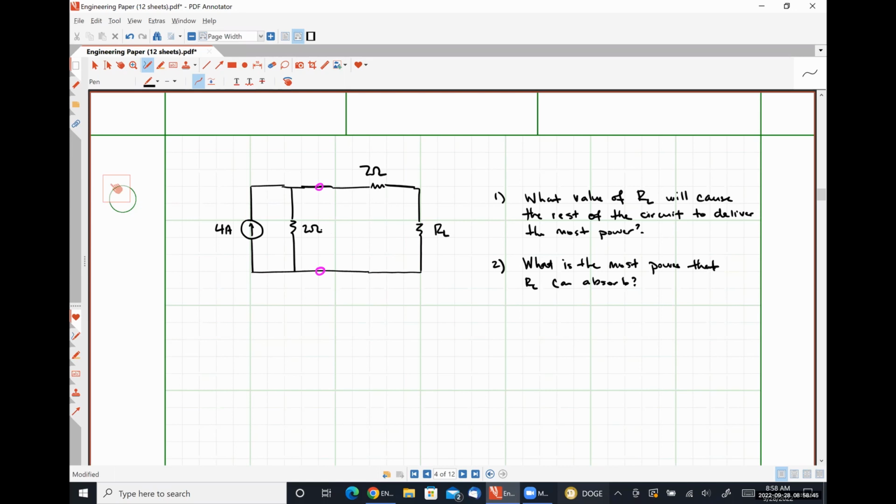This transformation is governed by Ohm's law, something that we learned on the 3rd day of class. V is equal to I times R. So we have I is equal to 4 amps, R is equal to 2 ohms. So 4 times 2 is 8 volts. All right. So 8 volts, positive polarity on top, in series with 2 ohms.